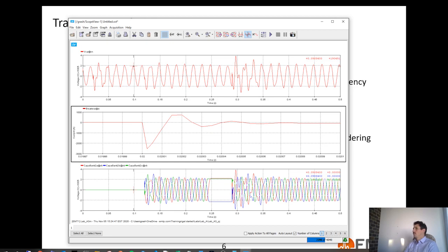20 is much better. Often you take the time step as small as possible, but the problem is the computational burden if you have too small of a time step. Typically you have an idea before you run a simulation what type of frequency you expect. For lightning, for example, you will use a time step of 1 nanosecond or 5 nanoseconds.